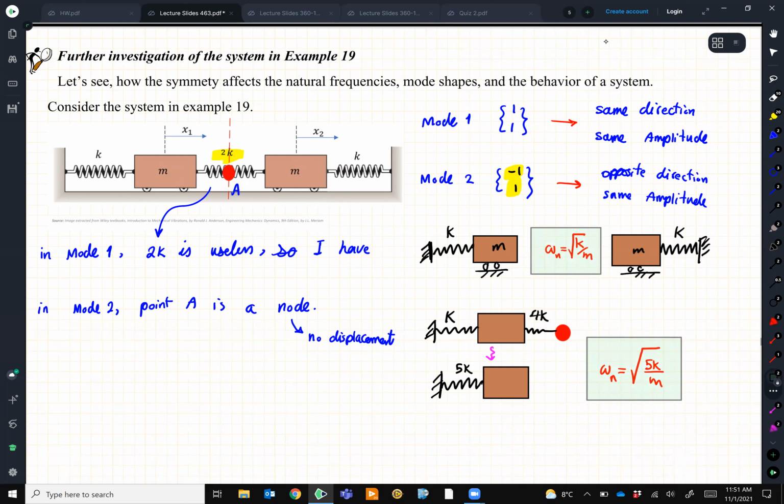All right. So why did we do that? Because single degree of freedom systems, or SDOF systems, are easy to deal with. We are familiar with them. We know what to do with them. Rather than solving all those matrices, we prefer to convert an n degree of freedom system to n 1 degree of freedom systems. And this is what we did here. Because with the 1 degree of freedom system, we know how to find the natural frequency, and done. Yes. Well, to find the mode shape, you have to do a lot of basic math anyway.